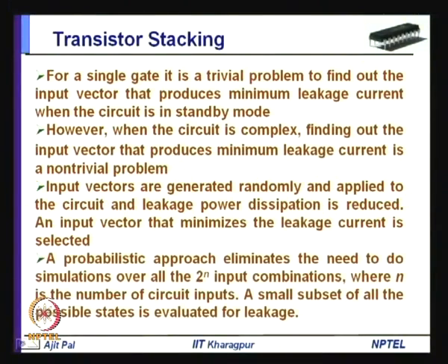There is another approach, a probabilistic approach, that eliminates the need to do simulations over all 2 to the power n input combinations, where n is the number of circuit inputs. A small subset of all the possible states is evaluated for leakage. This is essentially a heuristics based approach.